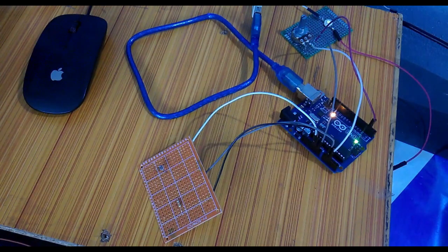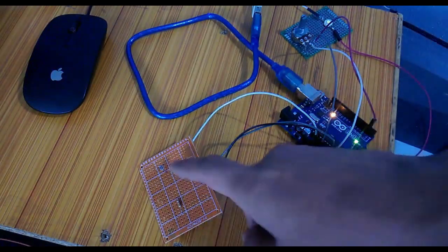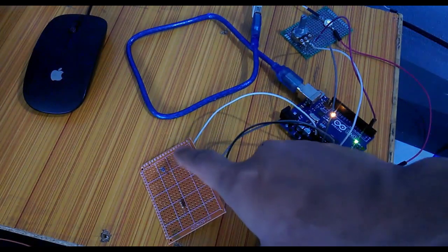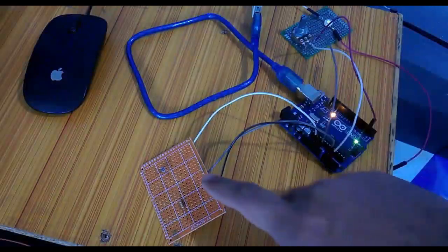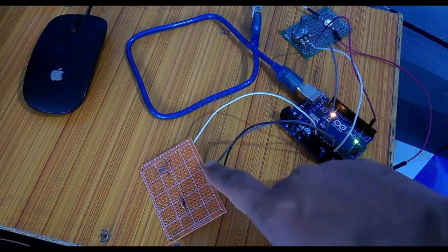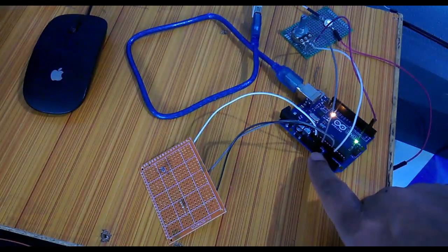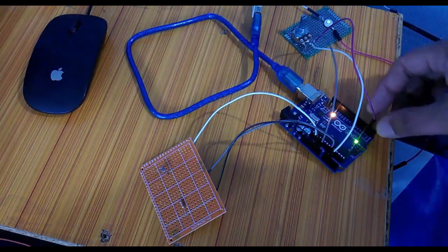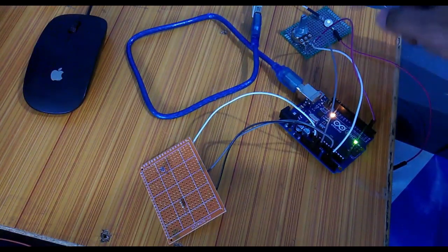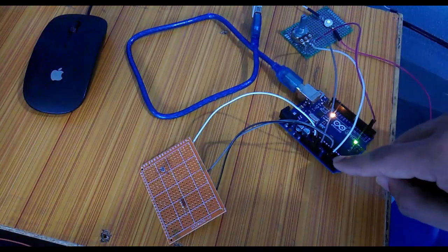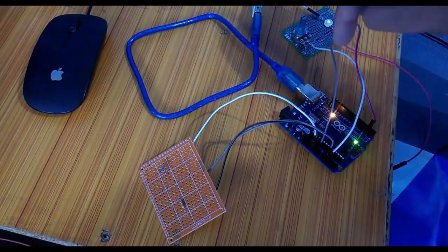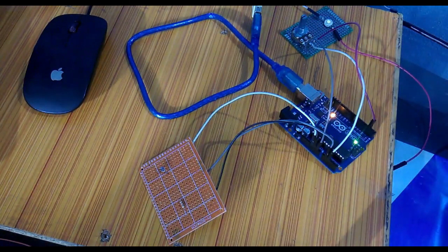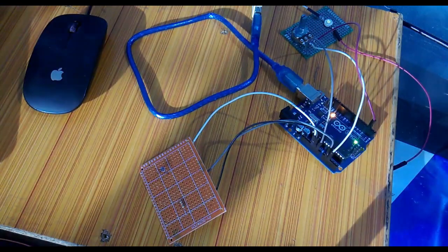Okay, so now my friends, as you can see, the components are interfaced. This is the LDR and a resistor which are connected in series. Now the white wire is connected with the 5V, the black wire is connected with the ground, and the gray wire is connected with A1 pin of the Arduino. Similarly for this variable resistor, the red wire is connected with pin number 2 because I'm supplying 5V from here, the middle wire is connected with A2 of the Arduino Uno, and the leftmost wire is connected with the ground of the Arduino. And now let's start the programming.